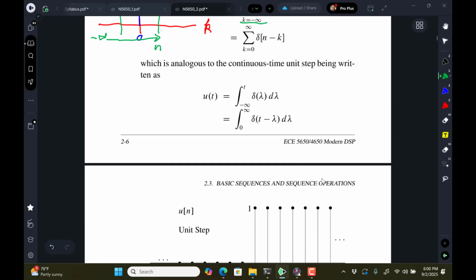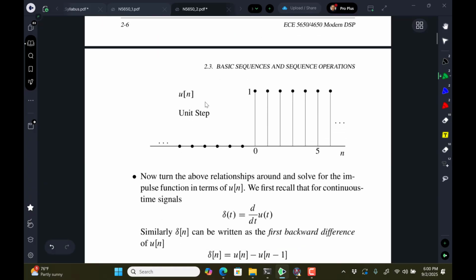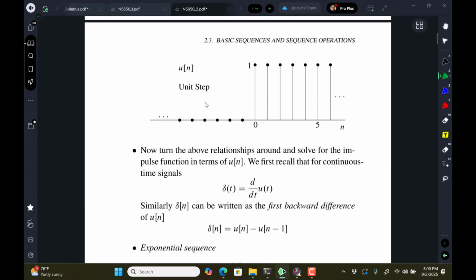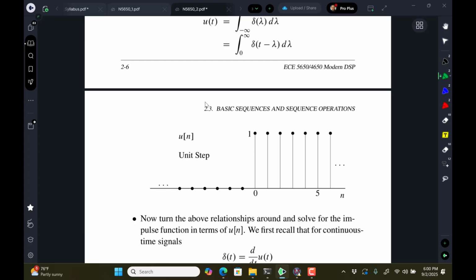And that's what this u[t] does, but it doesn't get defined at t equals 0. So it's not hokey, it's just that we have what I learned about in school when I took math classes, called operational math, an operational concept of math that is very convenient for engineers, but the fine points of it kind of break down when we have a 0 rise time step function.